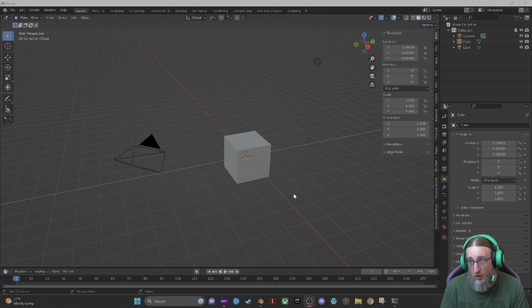You also want to make sure that none of your vertices go below that. You can hit 1 on your number pad, Z, and then wireframe. You can go into wireframe and then just scroll back and forth just to make sure no vertices are going below the bar that you currently have. Now that we have a face on there though, I can double click A where nothing is selected, and then we have our lithophane.